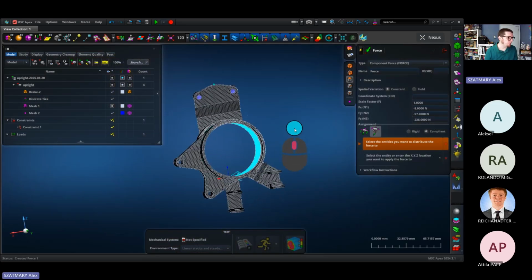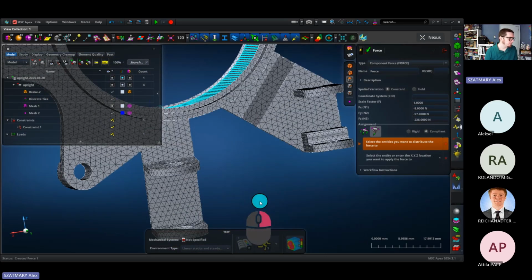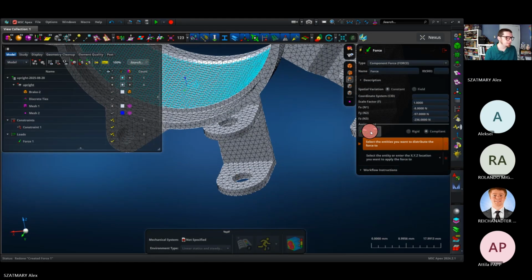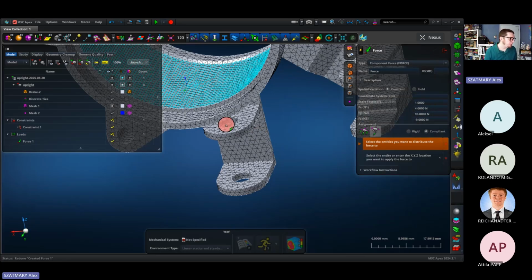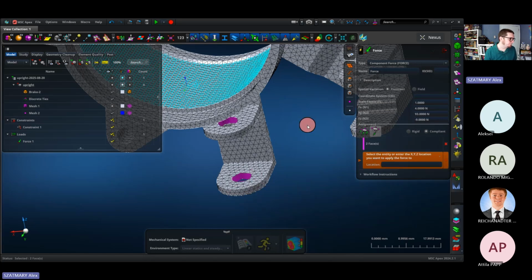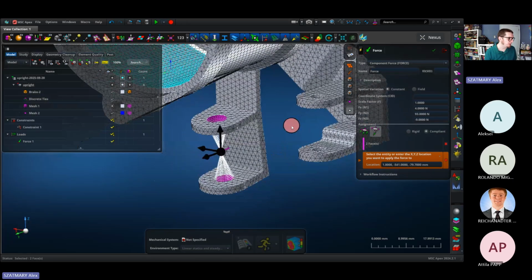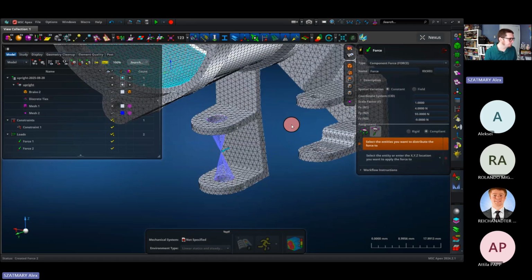Let's do this process again for the lower control arm. So let me zoom in there. And I'll enter my force components, 493, -9. And again, I'll pick those two holes, middle click, and Apex remembered that I'm going to want to be picking based on faces and average points. I'll rotate around. Yes, I have picked that average point. That's great. And I'll middle click to confirm.